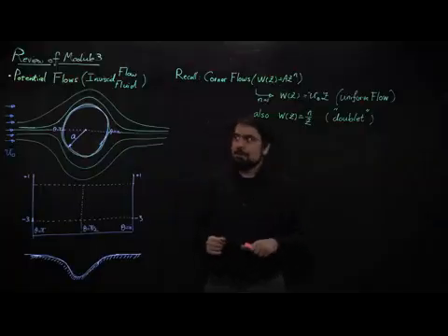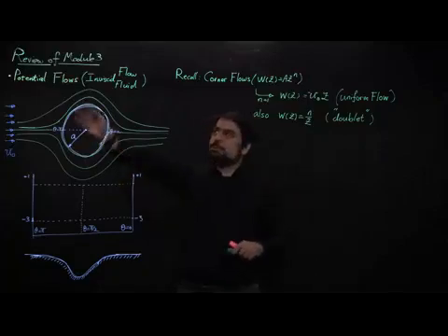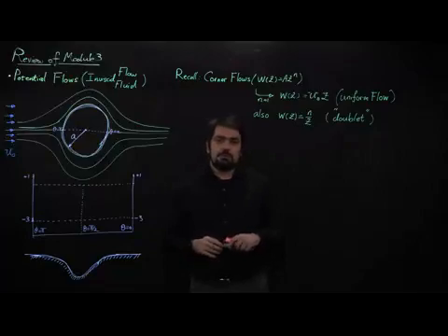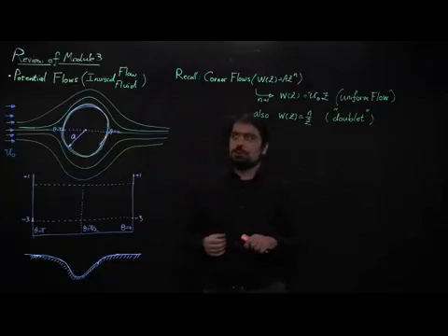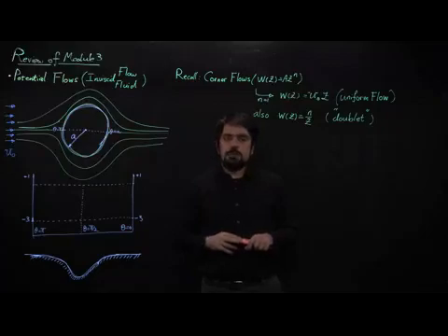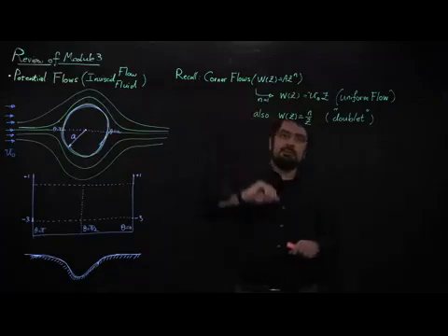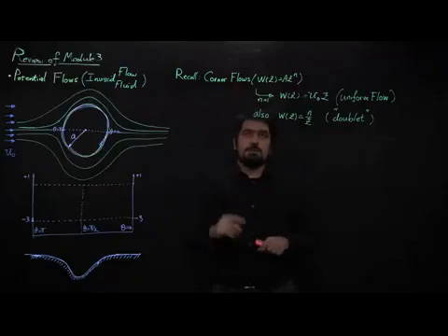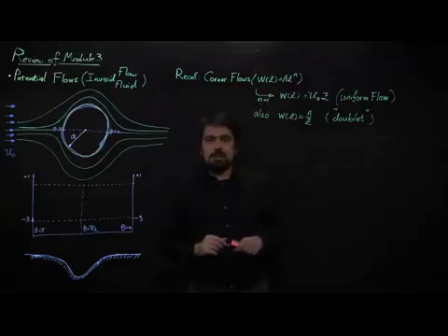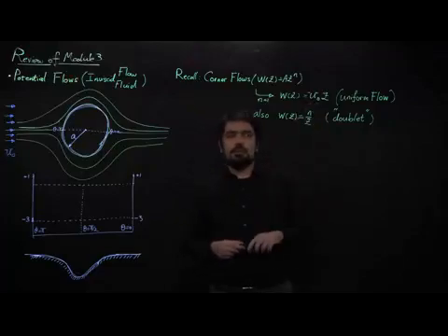Hi again. As you observed in the last video, we were discussing the potential flow and different aspects of potential flow. We mentioned that there's a class of different solutions to potential flow, that we usually characterize by their complex potential function, W(z). One class of these solutions is called corner flows that go as A times z to the power of n. For the case of n equal to 1, as you remember from your lectures, it gives us something very simple.